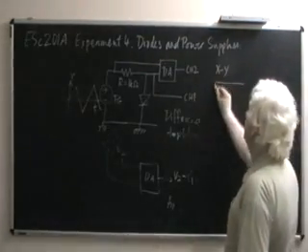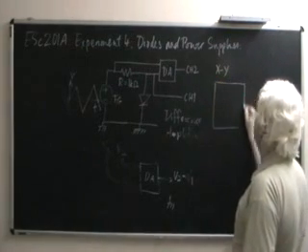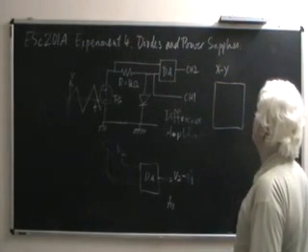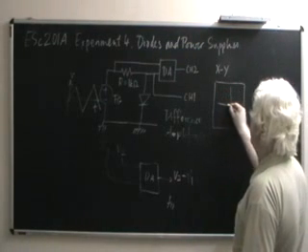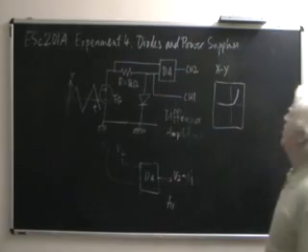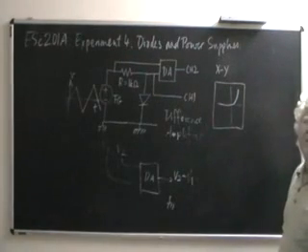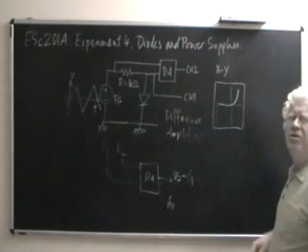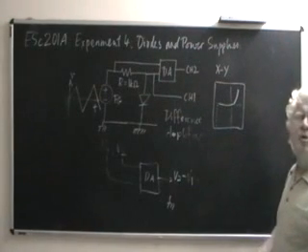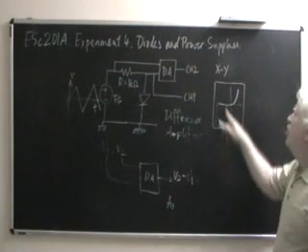see a plot after going through all the procedures of centering the dot and the screen, etc. You would see a plot that looks like this on your scope. This is what you would see. You would not see this part because, as I said, that is a destructive process on the diode. You do not want to see that.